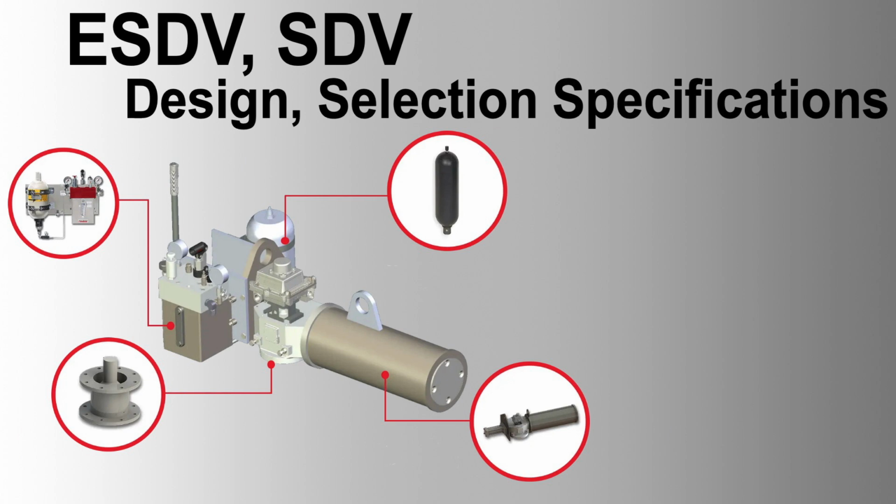Seat tightness must meet the specified bubble tight, Class X according to API 598, API 6D, MSS SP-61. Fire-safe design must comply with API 6FA, API 607, or BS EN 12266. Sour service compatibility, compliant with NACE MR0175. Safety integrity level, SIL certified according to IEC 61508. Actuator compatibility, ensure compatibility of actuator with valve in all respects, mechanical torque, etc. Lifting lugs, required on all valves including actuators exceeding 300 kg.